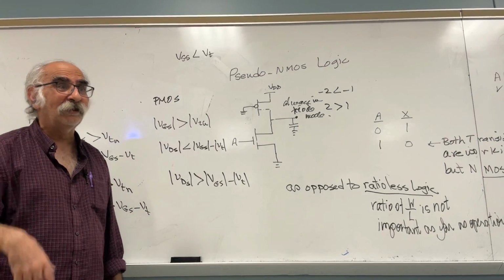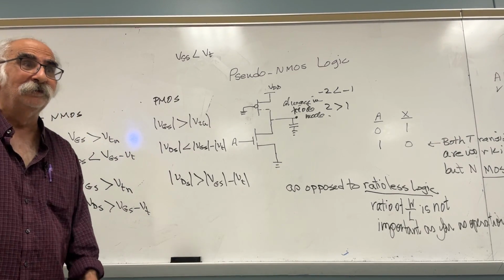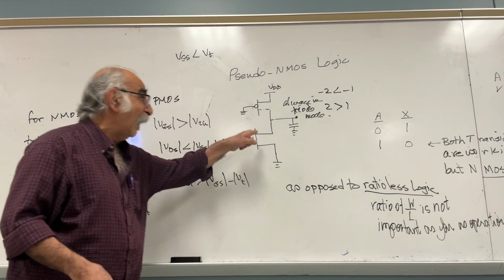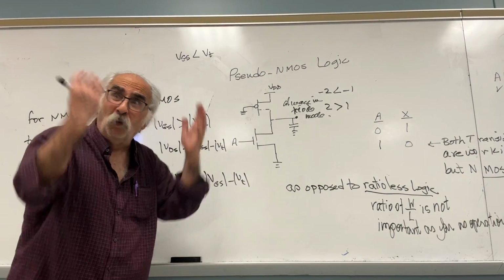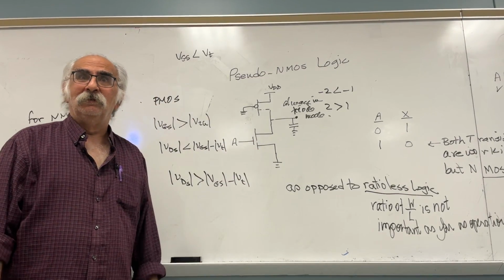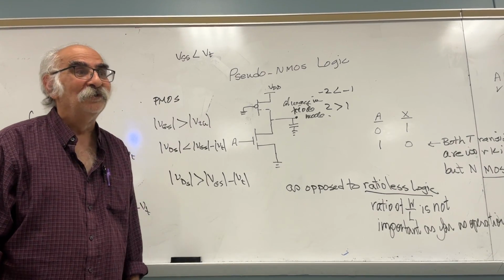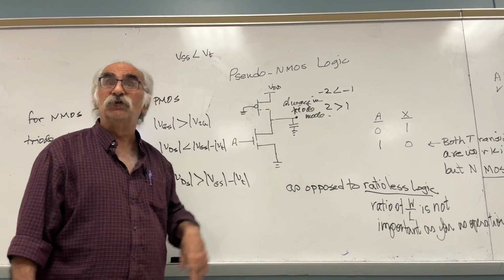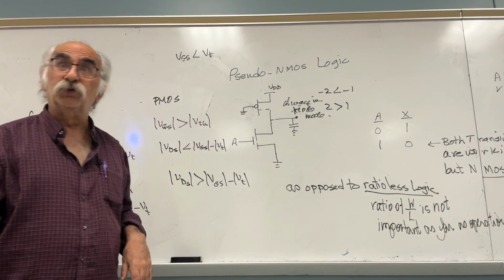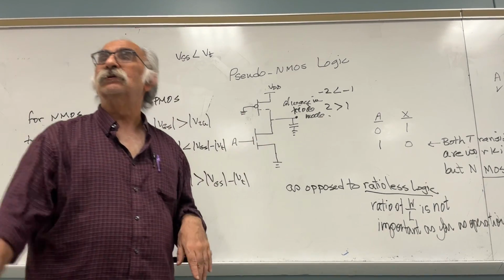Which current is higher? The saturation or the triode? Saturation. Which means what? I want this one to win the race. Yes or no? By proper choices of the W over L, we need to make sure that this one wins the race.